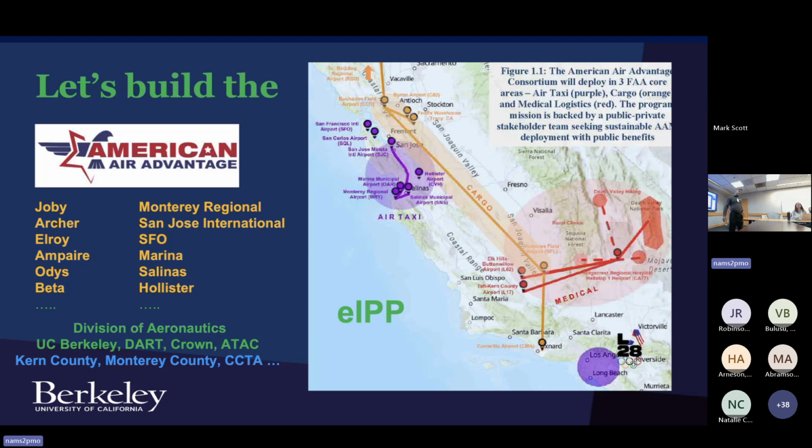In the regional airport case study, what we did is we maintained 3 nautical miles of separation between these aircraft. 5 would be ideal, but we couldn't make it. Everything is flowing from one airport to another, so we just said there's a route like this, and we keep 3 nautical miles of separation. If we cannot keep 3 nautical miles of separation, the aircraft doesn't take off.